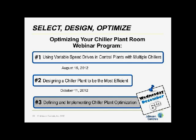Because when you lower airflow in a tower, the approach increases. And that's the reason why we use airflow to maintain minimum condenser water temperature. When you reduce water flow, the approach improves or gets smaller until you reach the point where there's dry spots in the fill, which is why we limit it to about 80% flow. Unless you've got weir dams, or if you've got double spray header, then you really want to stick to around that 80% point and honor what the tower manufacturers want.